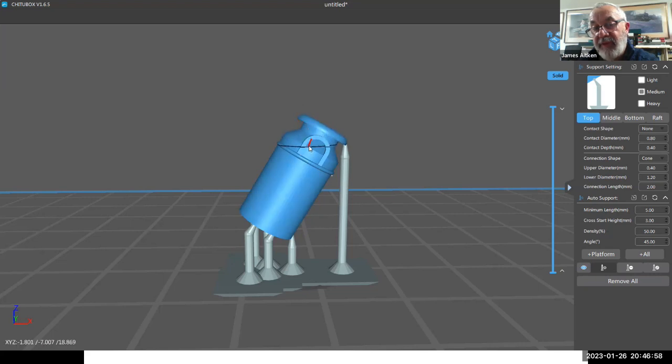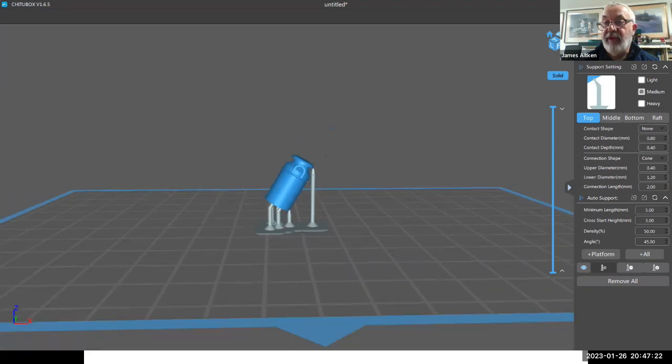Going back to Paul's observation: if you hadn't rotated the milk churn to 30 degrees, like you did with the bottom, where the first layer of the lid is, there's nothing supporting it all the way around the ring. It just becomes that first layer, and the edges have got nothing to hold them; they could sag.